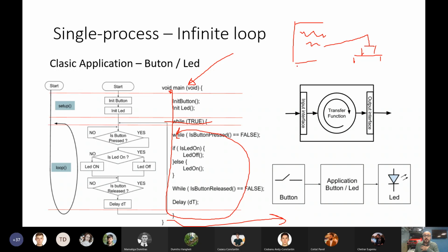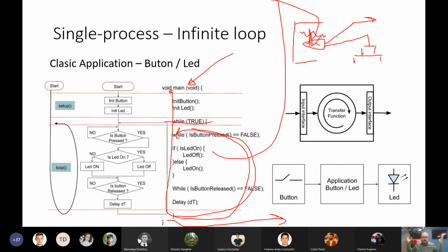Yes, you didn't, but this line of code somehow can be related to activating a pin that is connected to this button, let's say as a joke, but who knows? Because this code is random code that can be located in the memory. In this case, we should keep the processing under control. This is why we have the infinite loop here, because we want to bring the processing back under our control and not have execution somewhere in a random area.